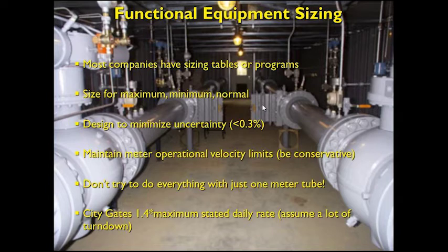Also, if you have relief valves, you don't want those to be placed under the high power voltage line either, or upwind of the high voltage lines, where your gas plume could be blown downstream into the high pressure lines. And getting in and out of the facility, you need an all-weather road. Most technicians drive a truck that's loaded with every tool that they ever bought, and there's a good opportunity for getting stuck if you don't have good conditions.